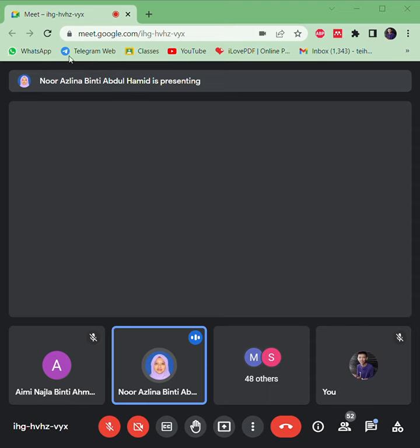According to the Ly, parallel to the Ly, this is how the load transfers. This half of the load will transfer to beam BD. Another half will transfer to beam AC. So it is just directly split into two, which is 0.5 of the load from the Lx transferred to both sides here.